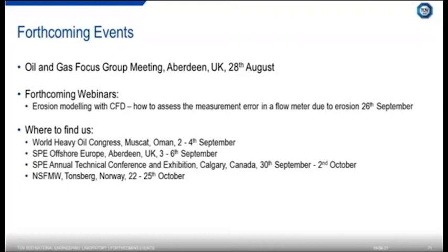Oscillatory densitometers tend to be a cheaper and, if properly calibrated, more reliable way of doing it. So for certain applications, they can be used. They might be useful for things like particularly viscous fluids, or perhaps slurries would be an application where they would be a useful technique to use.